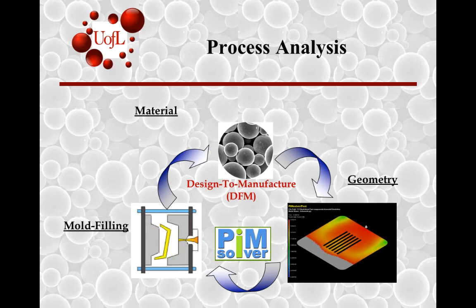In order to look at designing for injection molding, you have to combine materials and their properties with process conditions and also make adjustments to the part and mold geometry. These are iterative solutions, and so they are best computed using digital tools.